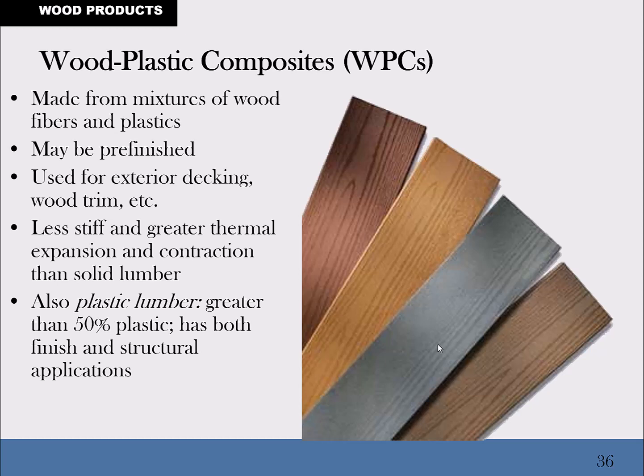It's a plasticky material that actually has some wood fiber in it. They're taking the sawdust and recycled plastics and making a decking board, which is a pretty good idea. But that stuff does expand and contract quite a bit. It works pretty good for decking compared to siding, because you can have gaps in the decking to allow it to expand and contract and to keep it from buckling.